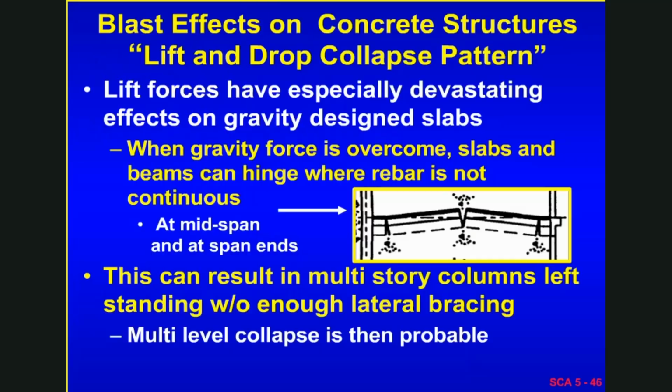The effect on concrete structures of the lifting force of a blast essentially sort of goes against the way a so-called gravity design of a structure is done. One places reinforcement steel to resist forces coming from the top by the weight of the structure and the weight of all the things, the occupants that are on it and the furniture and so forth.